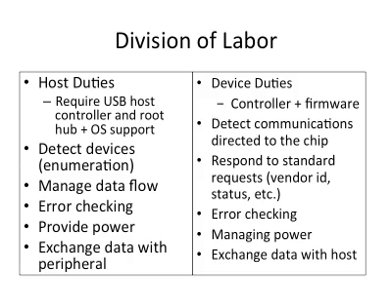So we know that for USB communication, we need a host side and a device side. For the host side controller or hardware, you need a USB host controller and root hub plus some operating system support. The responsibility of this host side USB controller is to detect devices.